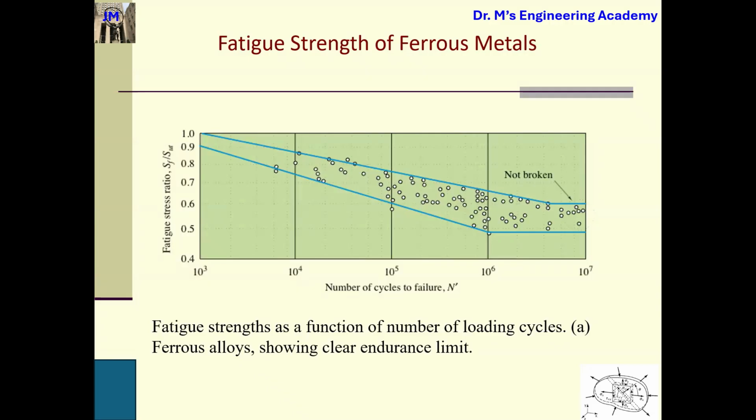This equation says that if I know the fatigue strength or the stress level I have, I can use this equation with S_L prime and S_E prime, which depend upon the material. Using this equation, I know the number of cycles to failure, that means the fatigue level of this material. Questions so far?